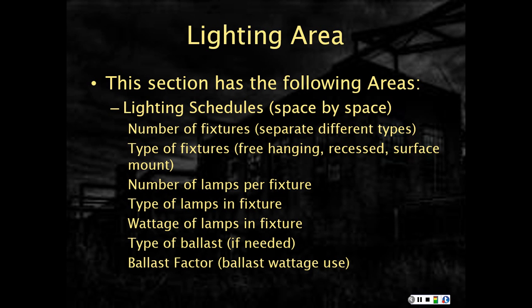How many lamps are there per fixture? The type of lamps in the fixture, so fluorescent, incandescent, LED, HID, what are they? The wattage of the lamps in each fixture. Now, depending on the lamp, if they're fluorescent, all fluorescents have ballasts, with the exception of inductive lamps. The type of ballast, if needed.